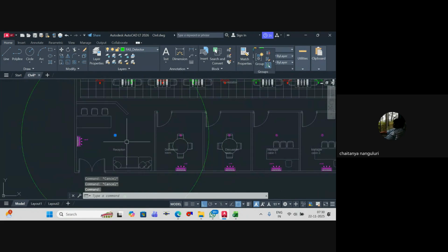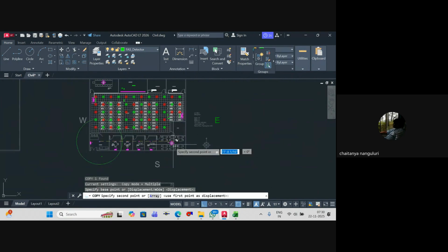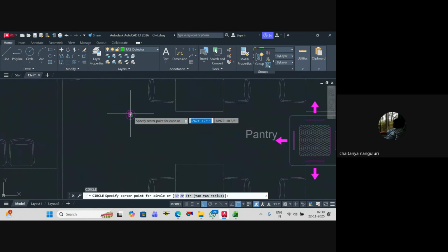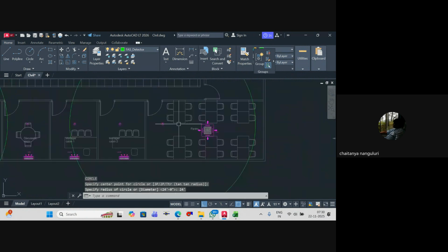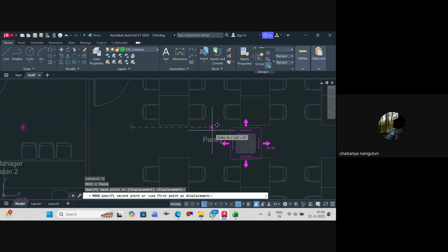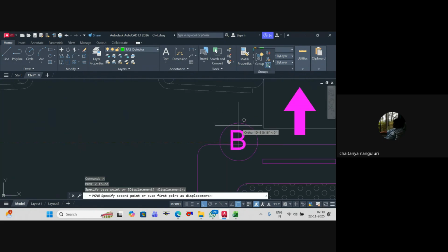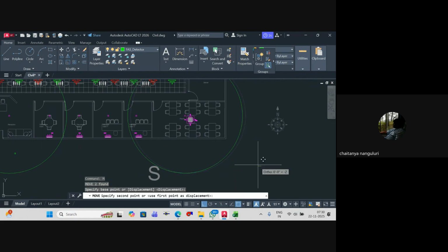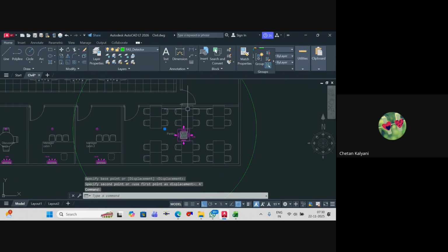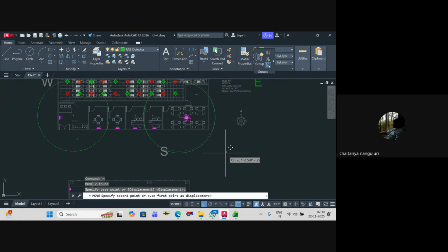In this room, let's see. Five into 3.28, that's around 24 feet. So it's better we take this one at the center. Yes, but I have your air supply. So between that, I shouldn't have within 1 meter. You agree? Yes. 1 meter is 3 to 4 feet, let's say. So I'll place it over here. Even then, is this sufficient or not? Yes, sufficient.